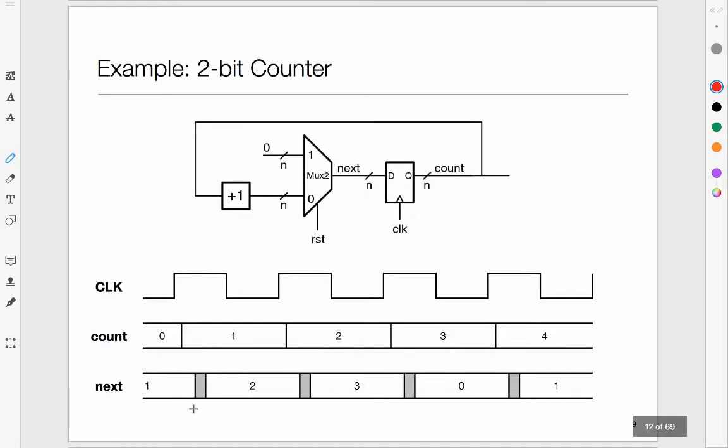So these regions where a multi-bit signal has neither the old value nor the new value are usually shown in timing diagrams as a shaded region. Essentially we are saying that there is obviously some digital value there, but it's some gibberish that we don't know, which will depend upon the very specific delays being observed. So this is basically a way of indicating that.